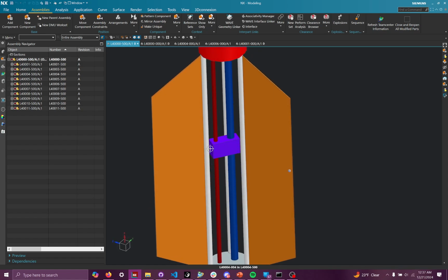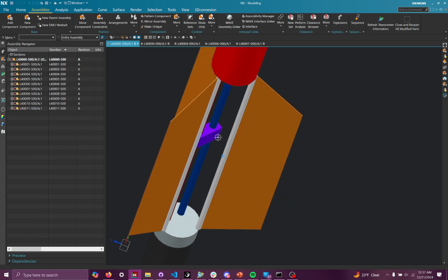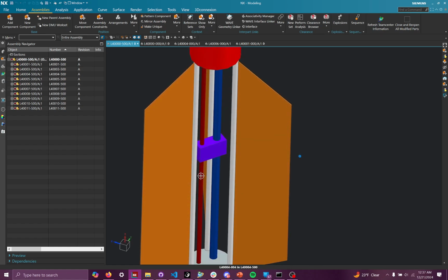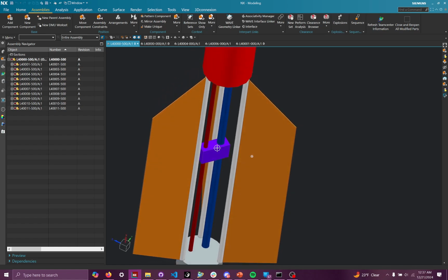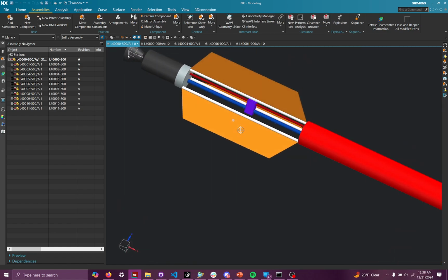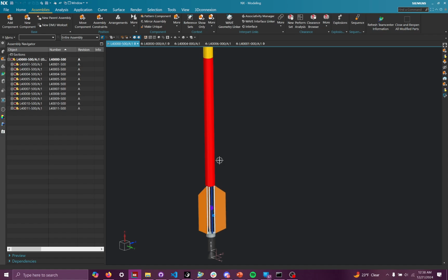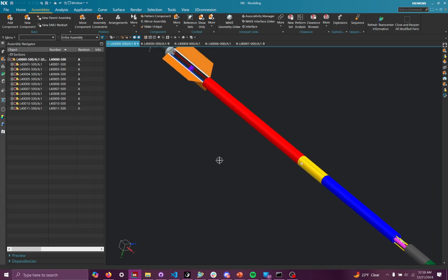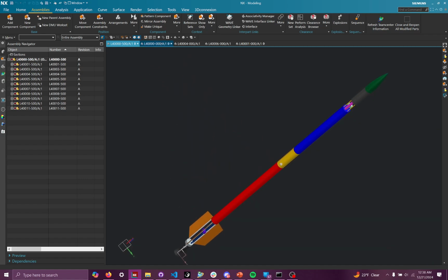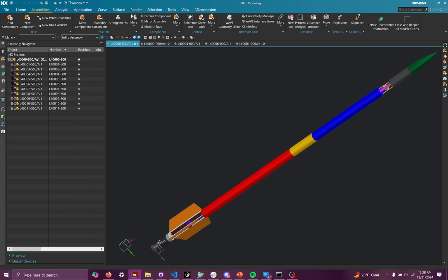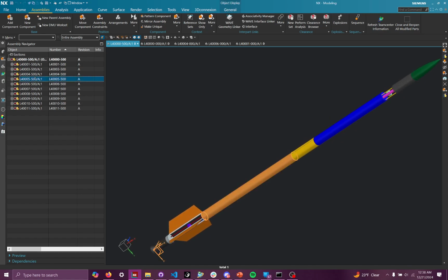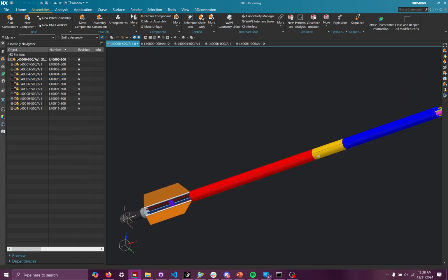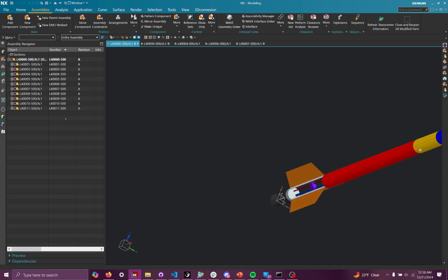You don't see the datum because I didn't bring that over. I didn't link that datum that I used to base the sketch off of. I only linked in the geometry I made, and that's pretty much it. That's how you make parts within the system. It's pretty easy the way it's set up. You just have to know where you are within your assembly navigator tree. I think that'll be the biggest thing, is just being aware of where you are, because if you fall off the bus a bit, it can be pretty messy to get back on.